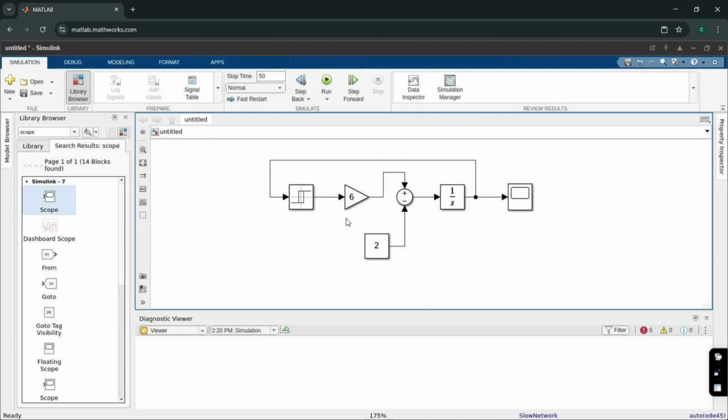At the same time, a drying factor continuously reduces the moisture to simulate real-world conditions. As the moisture level rises and reaches the threshold, the controller detects that sufficient water has been provided and turns the pump off. This process repeats continuously, forming a feedback loop that maintains the soil moisture within the desired range.